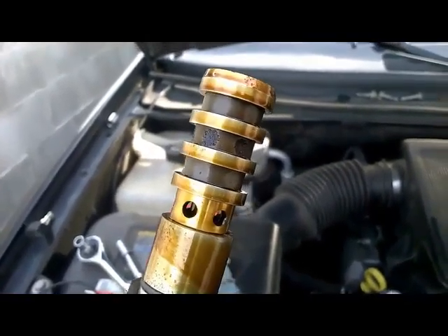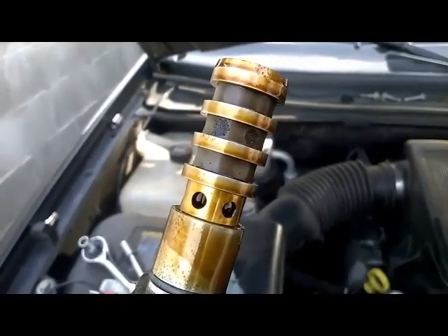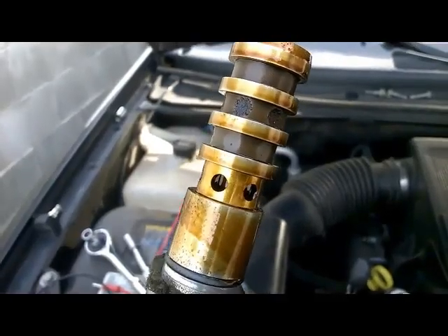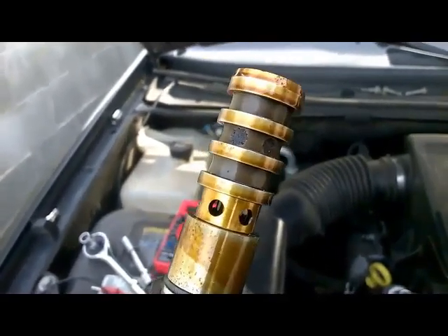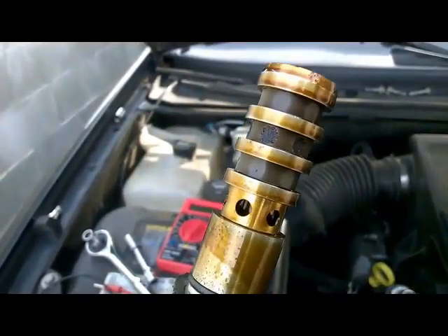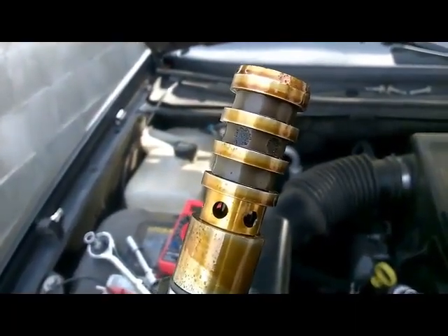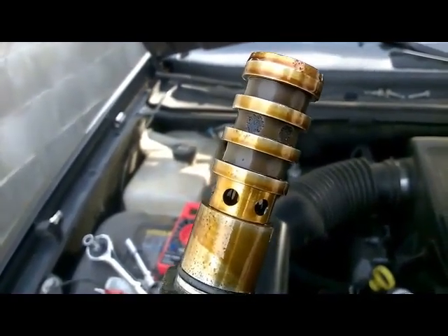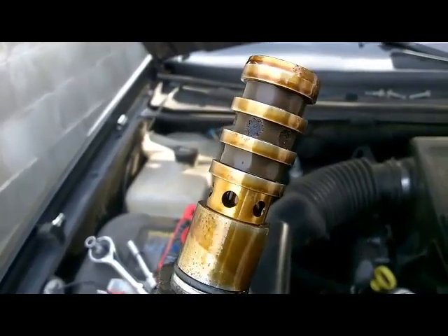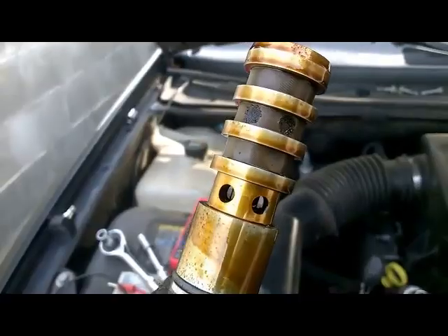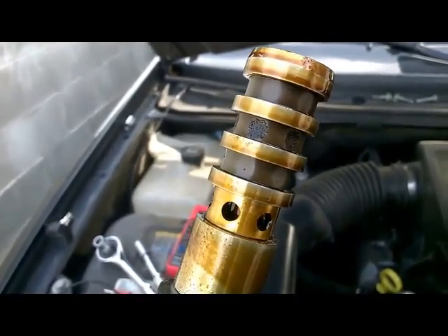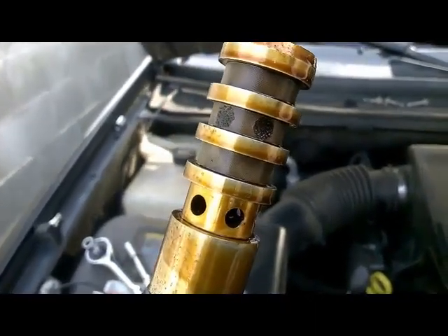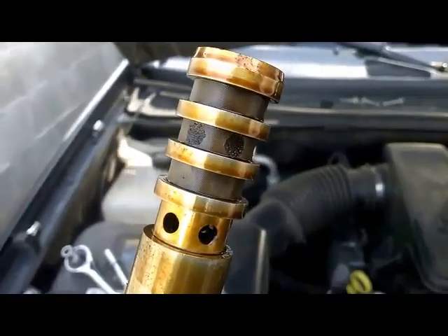All right, guys. So I'm gonna confirm with the customer to see if he wants to replace it brand new, or like I said, maybe just clean it. But if you replace it brand new or clean it, once you put it back, make sure to also replace the oil, because dirty oil will cause these screens to get clogged up. So make sure to do regular oil changes on your vehicle. All right, guys, so we'll see what the customer wants to do.